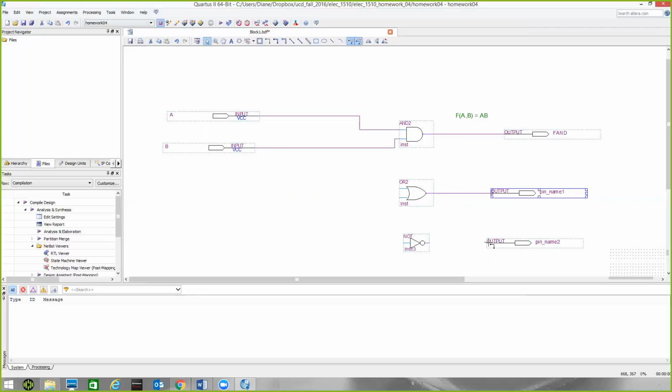Now, I'm going to wire this by hand, and I'm going to show you something that can cause you error. So crosshair there, hold the left mouse down, drag, and I'm going to drag this way into here. I'm going to hit escape, and notice when I went too far into this gate, I've got this big purple dot that stands for junction, and then I've got a tiny little wire with an X. That can actually cause some problems with your circuit. It won't generate an error message when we go to compile our design, but we want to make sure we don't have something like that.